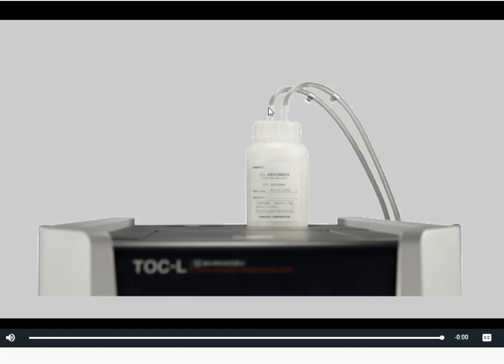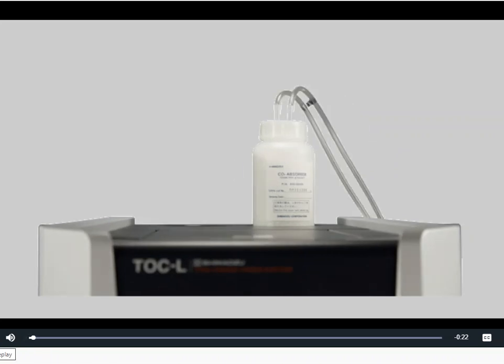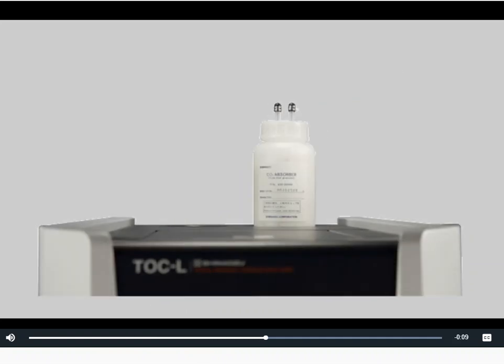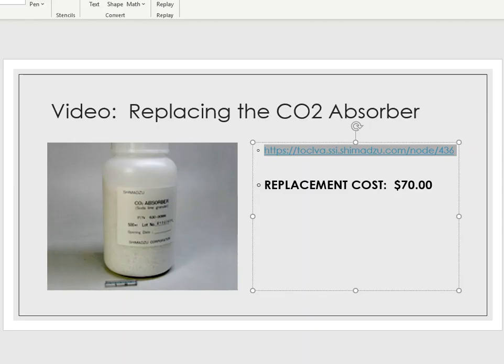If you didn't have that exit point and that second tube was not there, this bottle would continue to get air and CO2. And over time, of course, pressure would build up and it would explode the bottle. So we have to have an entry line and we also have an exit line. And that is the purpose of those two hookups at the very top. So again, it's just a simple matter: let's unplug them up here at the very top and let's replace the bottle. That's all there is to it, folks. And that is the story of the carbon dioxide absorber, or the CO2 absorber.